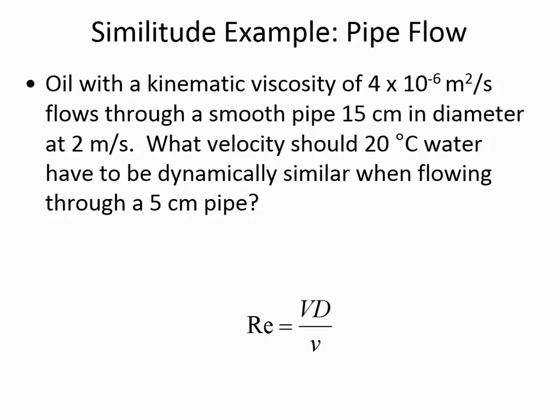Think about the blimp. We had to have a really high fluid velocity through the wind tunnel to get the forces high enough on the blimp. 100 meters per second may be tough to achieve. But what if, instead of using air at 100 meters per second, we could flood the wind tunnel with a liquid? Then that would allow us to achieve the forces that are required without having to have such a high velocity. Because if you use a fluid with a greater density, then you're not going to have the fluid moving nearly as fast to have the same force or friction on that blimp.